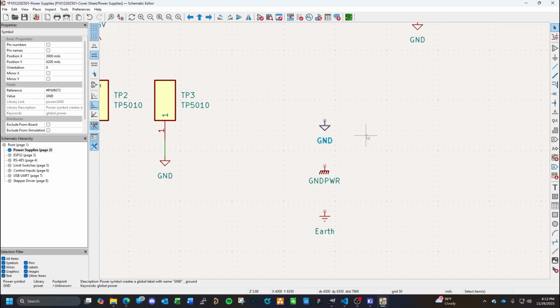So if anybody who's watching remembers anything from general electronics, let's get rid of chassis ground, because basically that's the metal enclosure the device is sitting in. Well, we'll keep it for now. Earth, a lot of times you'll use in an actual power supply, like if you're pulling in mains power from your 110 outlet, because that is tied to earth ground.